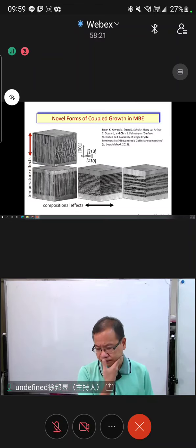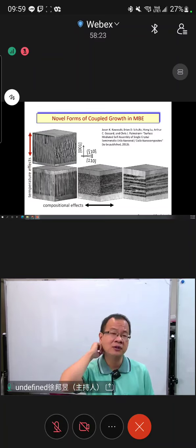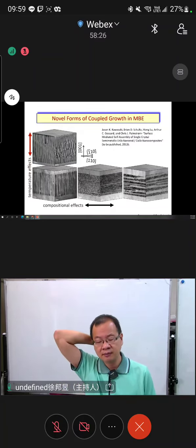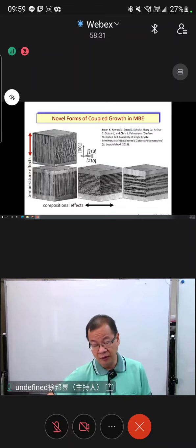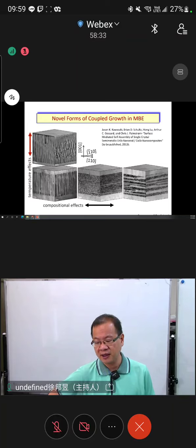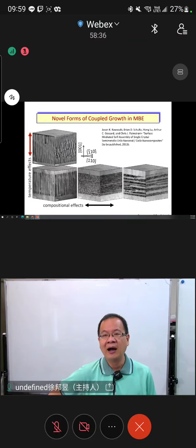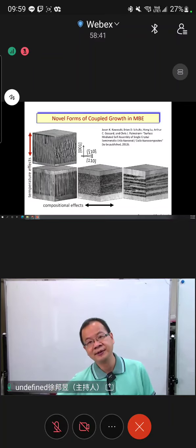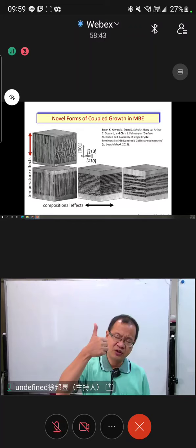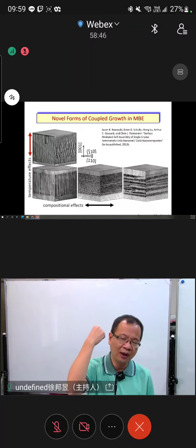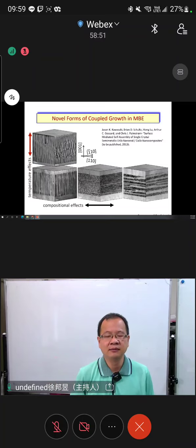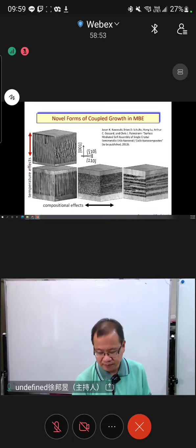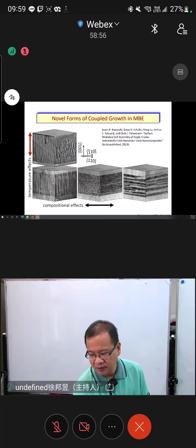And you can look at it. So on this page, you have crystal structure correlated diffusion, and that means how you grow. If your diffusion equation is the same, they grow by the same equation on the same crystal faces. If they are different, then it's different. So crystal structure, how they diffuse, driven by what effect, what's the thermodynamic driving force, and that's it. That's what kinetics is all about. So pay attention to the common part.